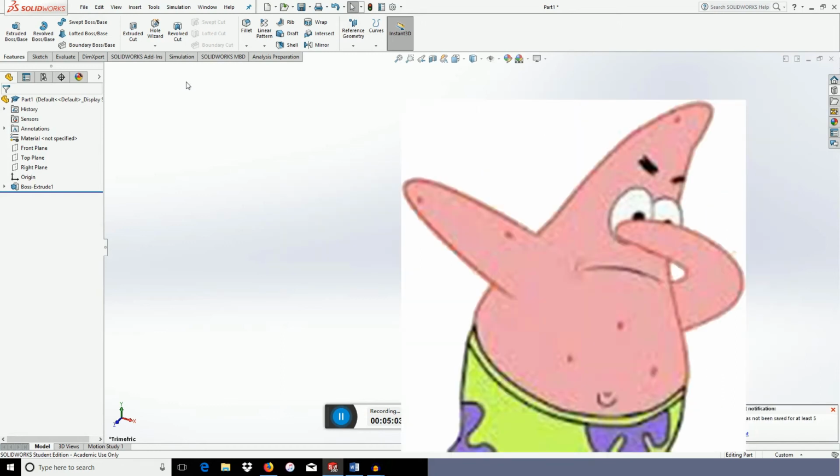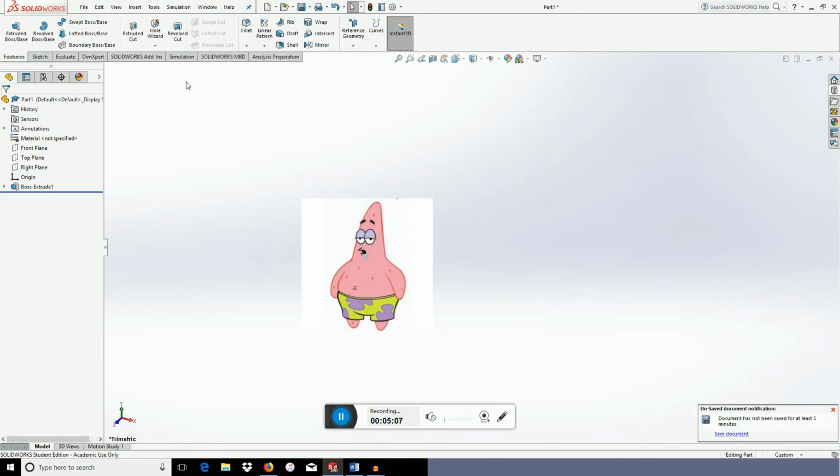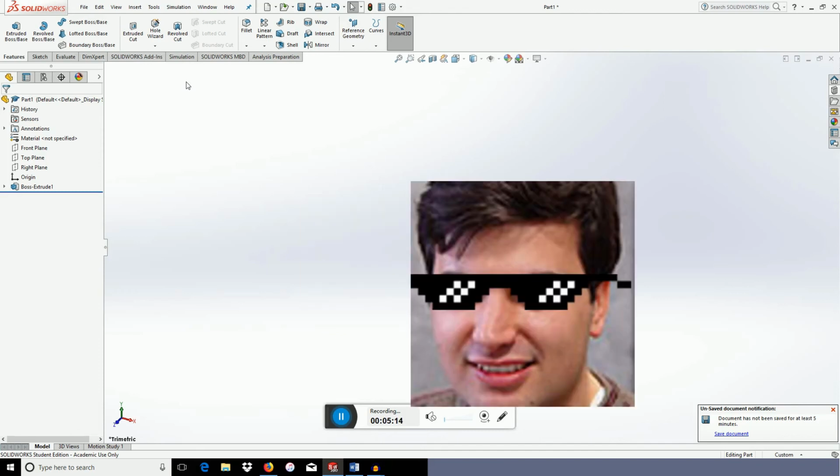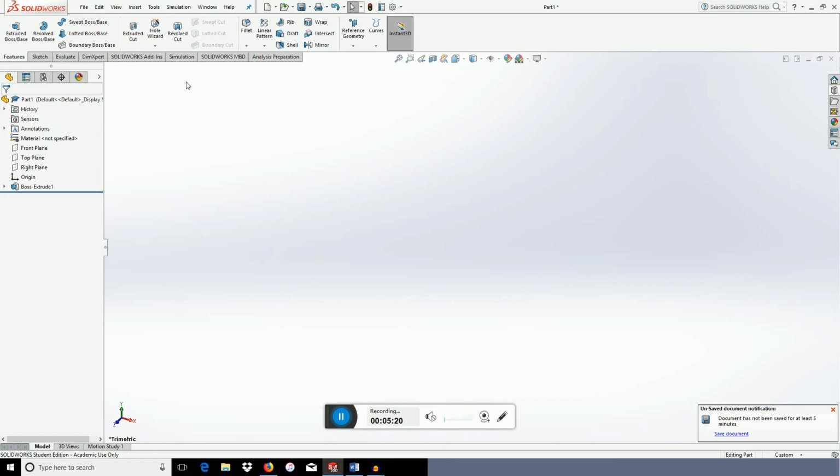As a rule of thumb, if your object is simple and only has rectangles and cylinders, use extruded boss bases. If it has complex or multi-dimensional cylinders, use revolved. If there is anything non-linear, non-orthogonal, or more complex, try to go for the other commands. As a note to more experienced users, for more hard or undefined surfaces, opt for the surface section.